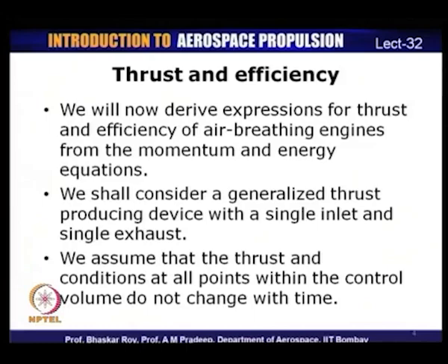So, how are we going to start our analysis? We will basically consider a generalized engine which has a single entry and a single exit, and then we will use the mass, momentum and energy equations, and that will help us in identifying the force that is experienced by such an engine as it consumes a certain amount of mass and expels a certain amount of mass, which also includes a fuel flow rate. So, what is the thrust developed, which is basically a force acting on the control volume.